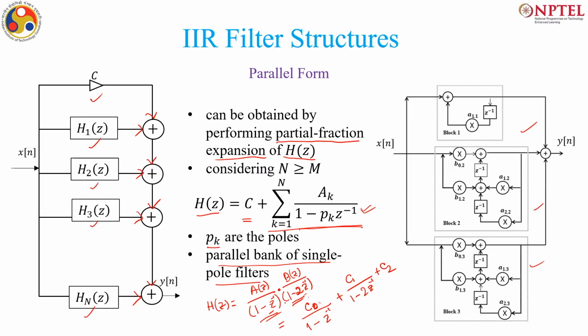for the FIR? Well, technically, since there are products and there is a denominator, you are able to break them into this partial fraction. But that is the IIR case. In the FIR case, if I have my H of z and I want to represent it as a sum of 2, it is nothing new, this is the same FIR filter only, because there are no denominators. Like if I have a polynomial in Z, and I break this as one filter and this as one filter, it doesn't really change, meaning that the direct form realization of the FIR filter is already a parallel implementation, and as such there is no separate parallel form for the FIR filter.